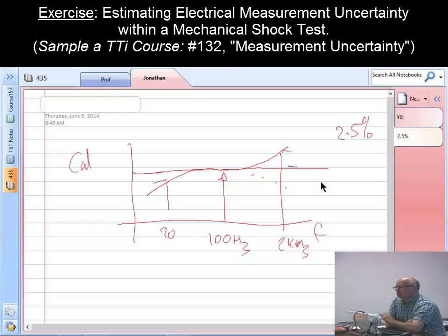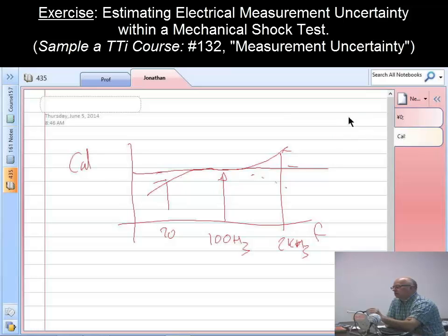It's always interesting to see that we have one sensitivity for the entire range, and yet we just ignore that and carry on as if nothing's happened. Imagine that in the world of gauge blocks, micrometers and such like, if you said this micrometer is only accurate at 1 inch, and if you got a half inch, you can have up to 50% error. But that's okay. That's what we do in the world of accelerometers.